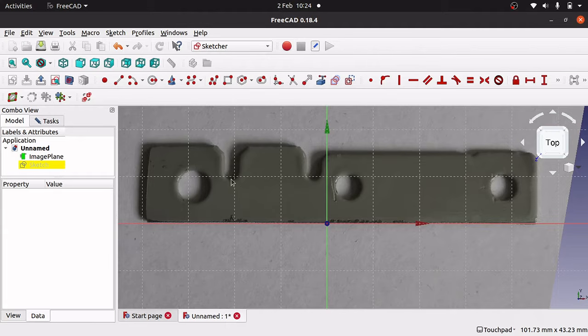I will create slot geometry in here, circle geometry, and use square geometry to surround this. Something that's a bit more complicated, I'll start using the polyline, but I like to keep with the basic geometry first and then backfill with any polylines or anything like that. Something a bit more complex.